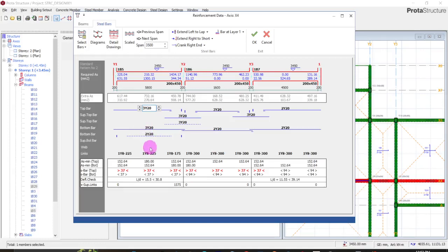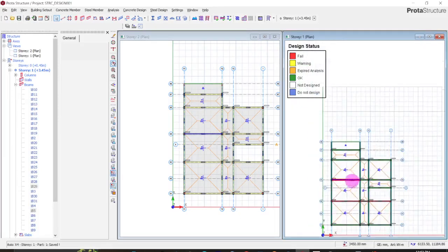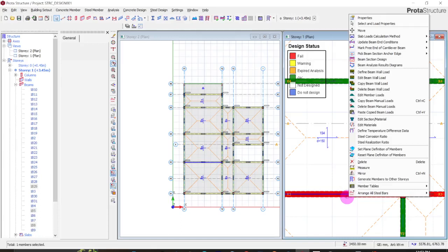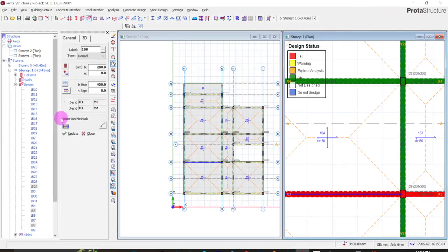Or maybe you increase the size in this case, because there are too many reinforcements. Is it allowed to bundle two reinforcements together? Okay, no. I like that you just separate them because you also need space for concrete. Instead, I can simply increase the depth to 500.